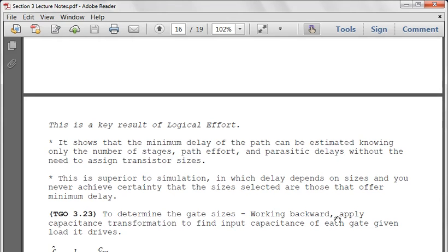So let's say you're designing a thermometer that has to meet a certain performance metric. You have an 8-bit binary input from a sensor that sends the temperature. It comes in, you need to store it in a register, and you want a Celsius to Fahrenheit converter, and some test beds in the circuit as well, so you can test to make sure the circuit is still working properly.